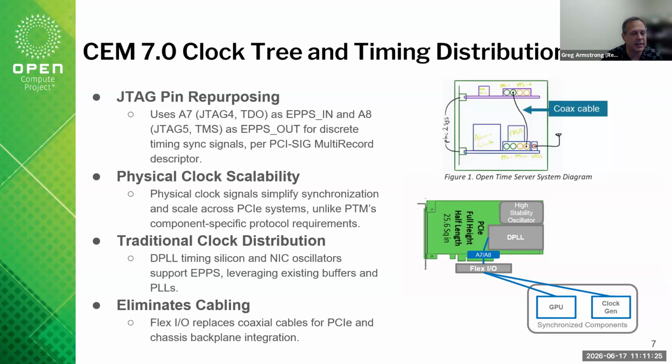Even if the interface is open, it just becomes a little bit more difficult. And so the PCI SIG has been looking at this as well, and with their card electromechanical standard in generation 7, they actually started looking at the exact same concept. But instead of looking at it as a full-fledged clock distribution with maybe some compatibility with telecom concepts, they just said, let's look at the best way to take traditional clocking and some sort of marker alignment and distribute it within the card.